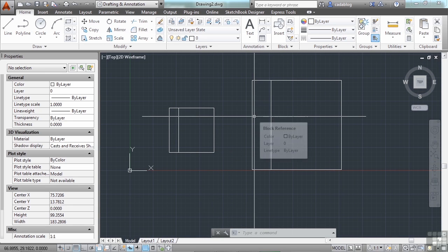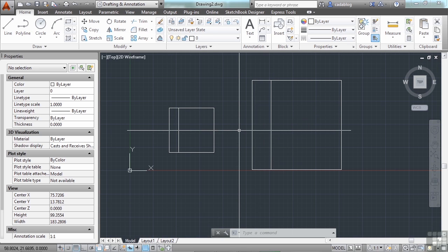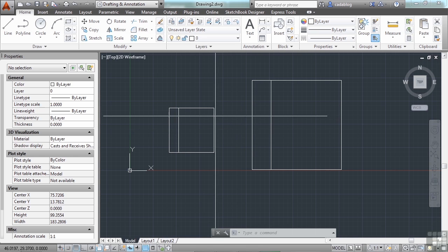Now, it's a normal practice to use the coordinates of 0, 0 as a reference point for a lot of different things. Site plans, architectural drawings, surveys, etc. Inserting a title block and other items at 0, 0 is also a common practice, especially when you're working in paper space. And when you create your block, keep in mind that every block's insertion point is located at 0, 0 of that individual block. Also, once inserted, a block can be copied, moved, rotated, etc., just like any other object.